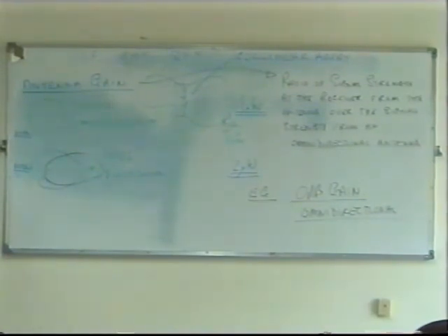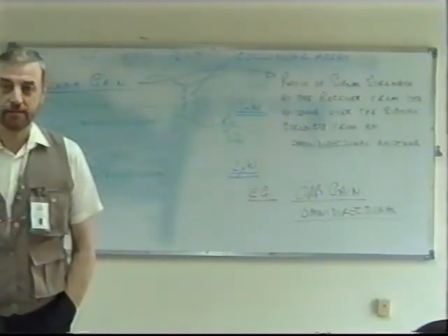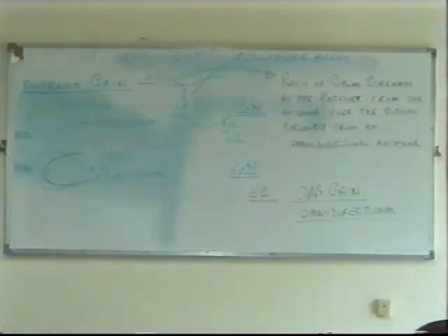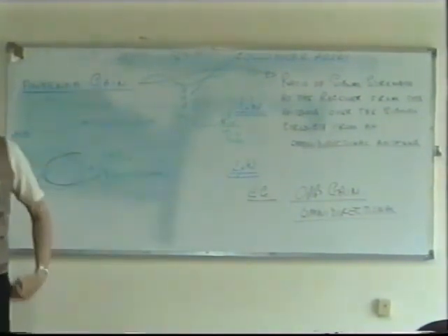So it's exactly the same as a 100 watt omnidirectional. What about 6 dB? Then we need a quarter, 25 watts. If you use 6 dB, it's a half of a half, or 2 times 2, so you can use 25 watts for the same signal strength at the receiver.